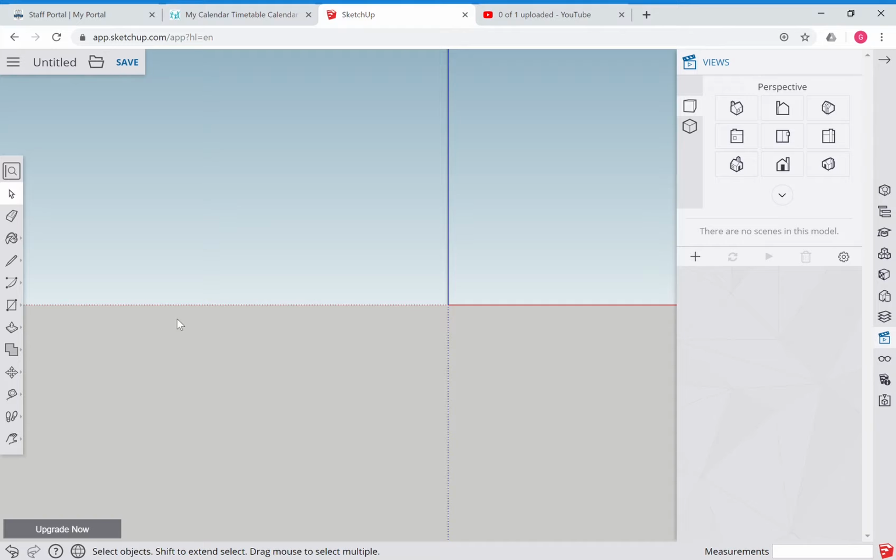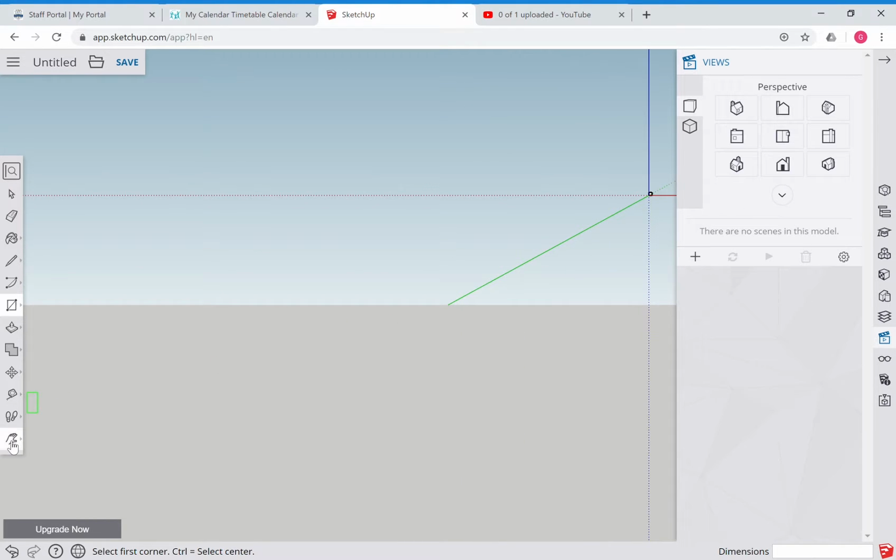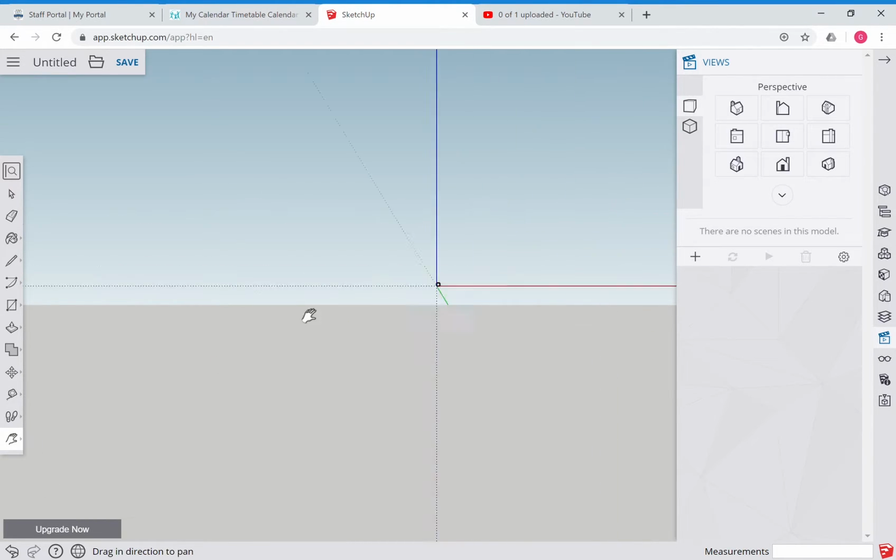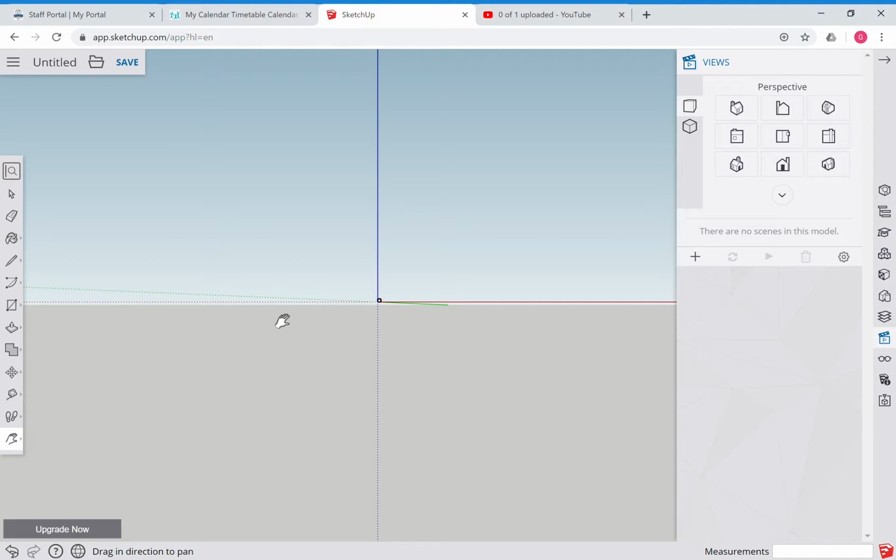Okay, so this is going to be another look at one more tool, and then we will start our process of designing our bridge. So we're going to make a couple of the members that we need to use. So we grab our rectangle tool, we're going to take this to the origin and go 6, 6. And we know that that's going to be very, very small, so we can just wind that back, grab our hand tool, keep the origin in the middle, 2 fingers on the mouse pad, drag them down,